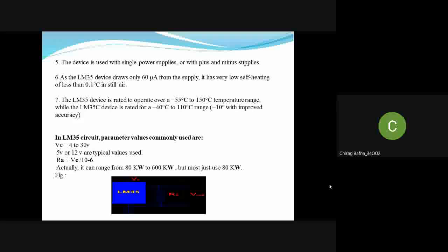This conversion is commonly called signal conditioning. As seen in the figure, signal conditioning can be a current to voltage conversion or a signal amplification. For example, a change of resistance must be translated into voltage in order to be of any use to the ADC.